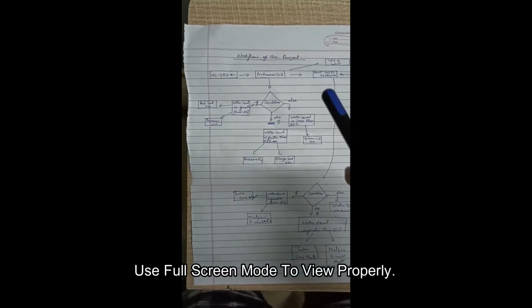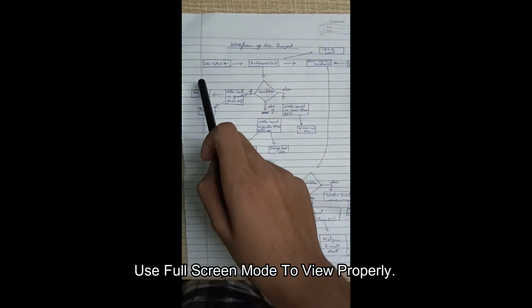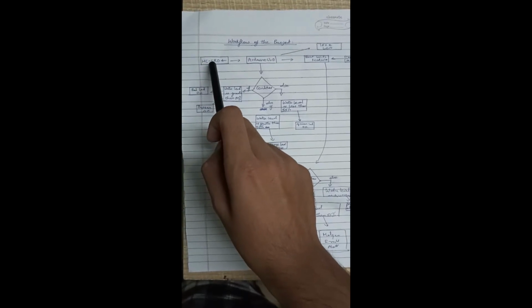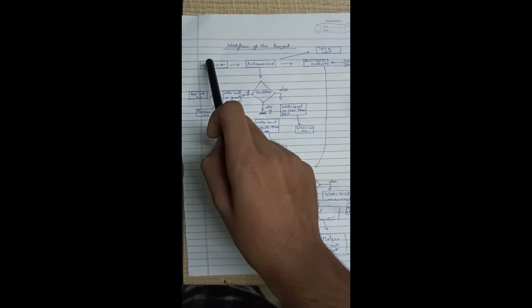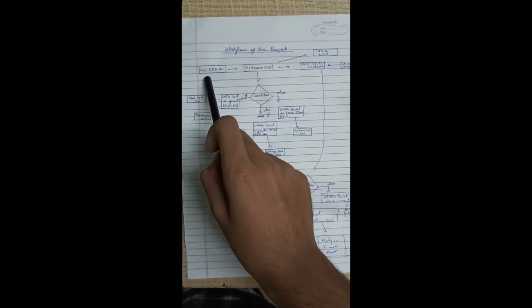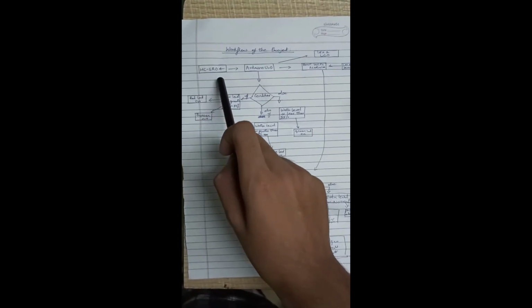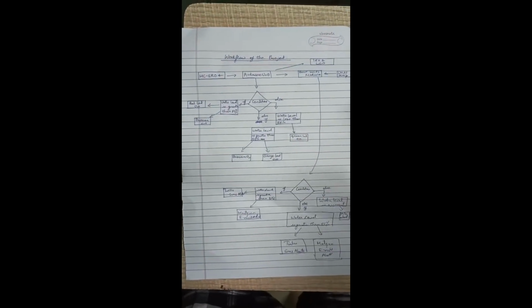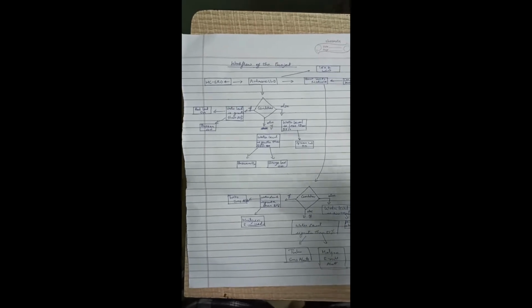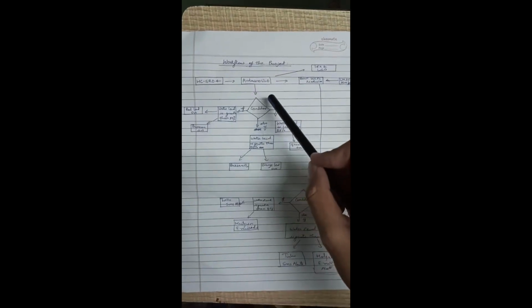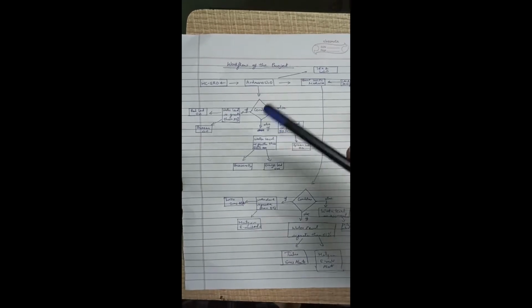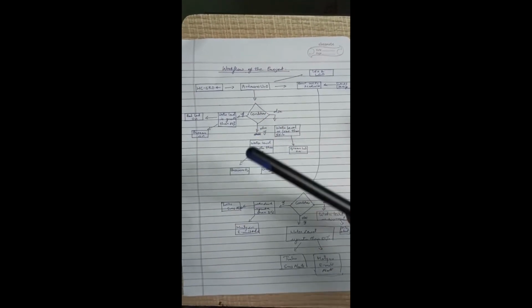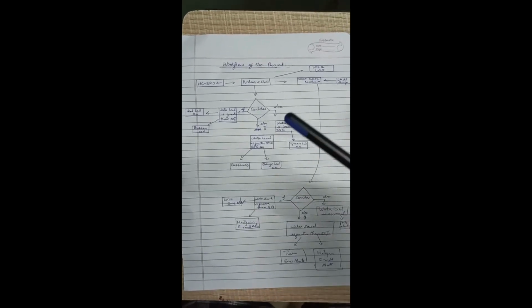Let's have a look at the workflow of this project. The SR04, that is the ultrasonic sensor, will be useful to measure the water level distance present in the water level tank. The SR04 will collect the water level distance in meters or centimeters. But I've used an Arduino code which will convert the distance into a percentage, which will be further used for making some important looping system, that is, an important decision making system.